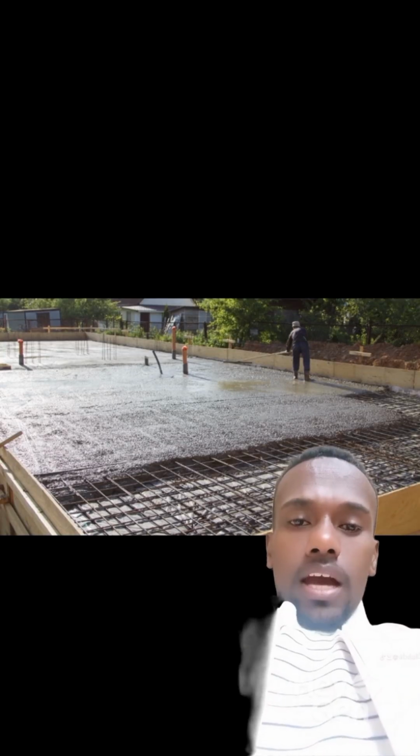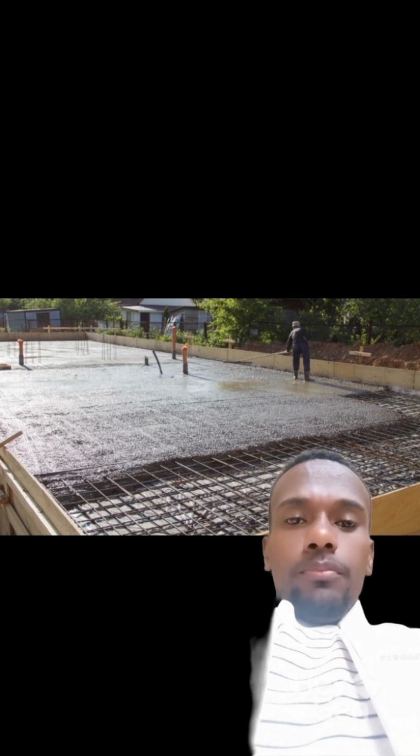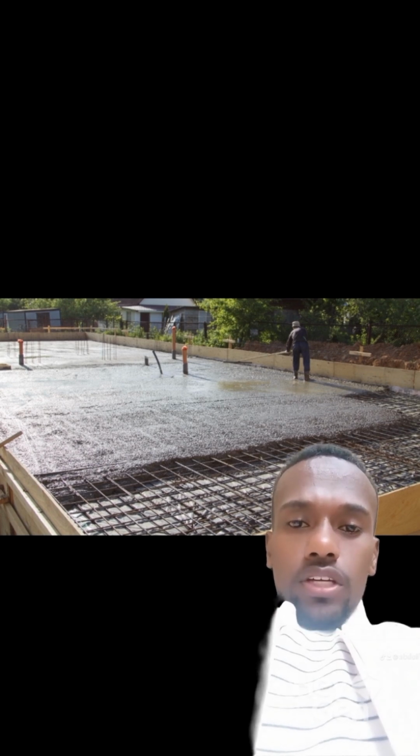Ground slabs are economical, simple to construct, and perform well for light to medium loads, acting as both floor and structural support. However, they are not suitable for weak or expansive soils or areas with high groundwater.